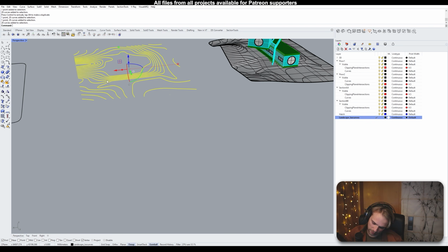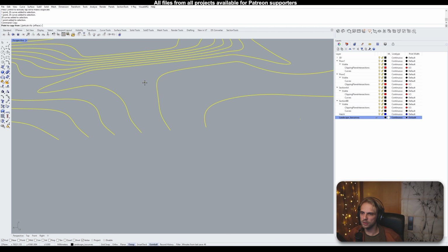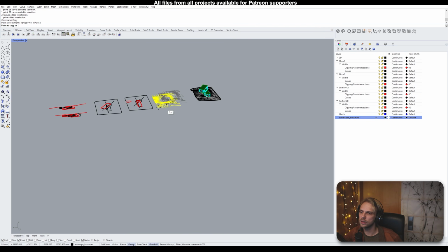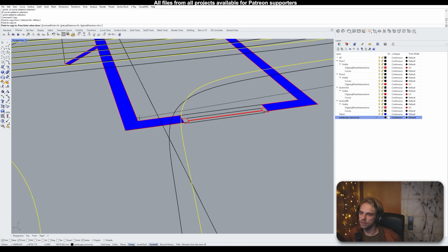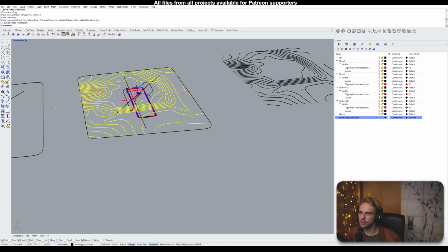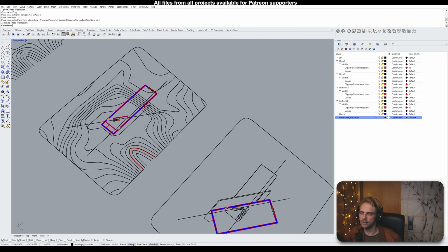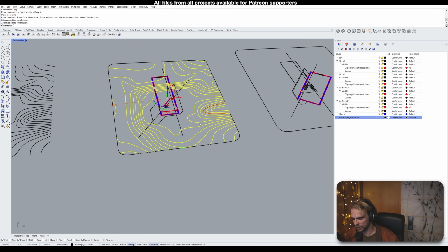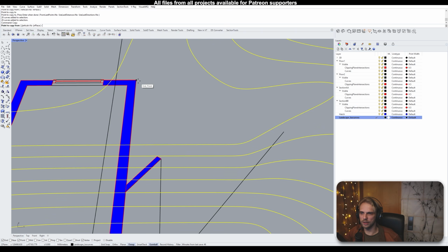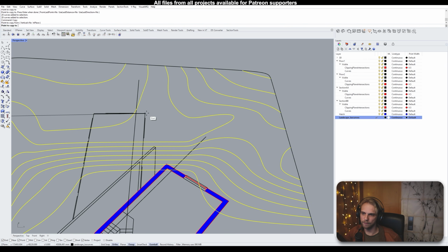So now the next step is to actually select this, type in copy, and copy it from this point. Don't forget to tick mark the point snapping in the object snap rollout. So we copy from point to this endpoint right here. And we get our beautiful contours in here. Some of them will need to be deleted, but others, they stay. So like that. And then we just kind of do it all over again for here.